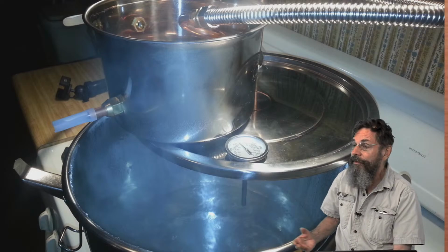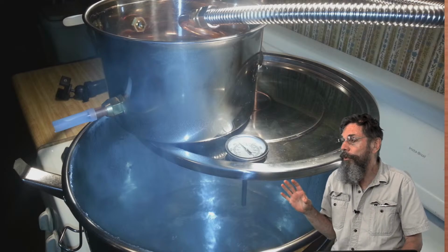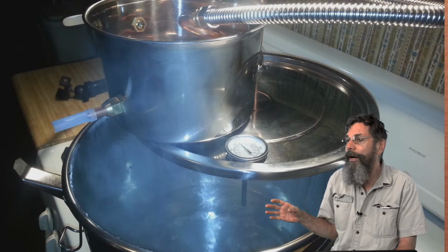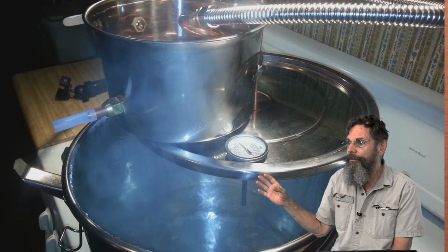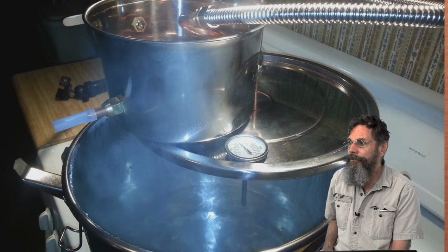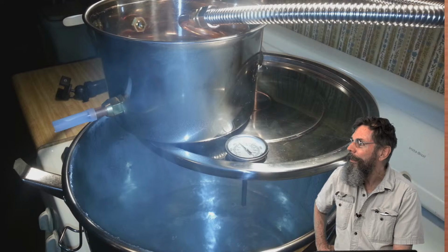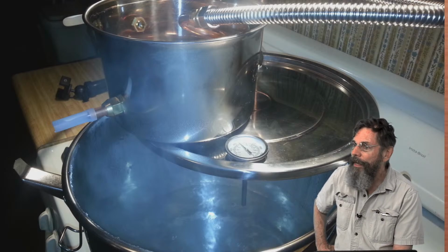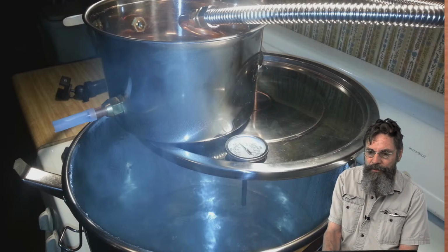So that's a safety thing I want to add in this, because some of you are going to be making these from cooking pots or whatever, or purchasing this online. These are available online, from our normal online outlets, either stores or our big shopping outlets, our eBays and our Amazons and all that. And some of them will not come with that unit. I would suggest you buy one of those pressure cooker relief vents and install it yourself if it doesn't already have one, just for safety's sake. Let me see what we got.